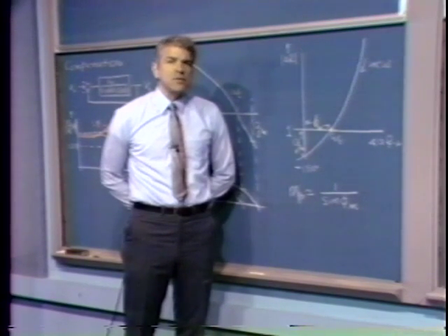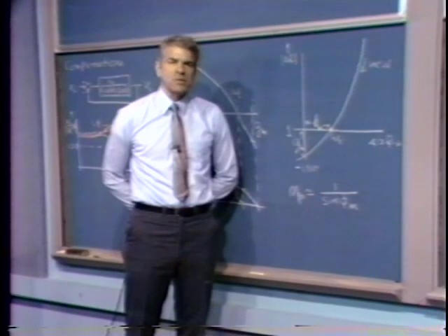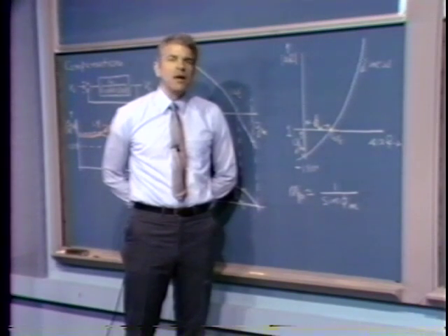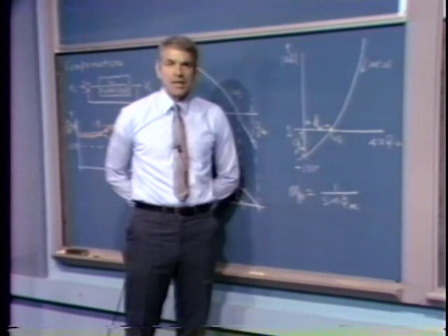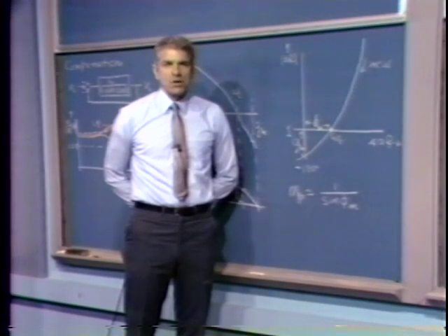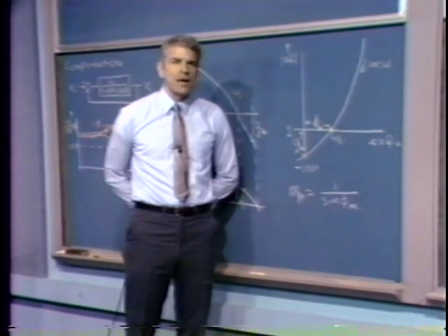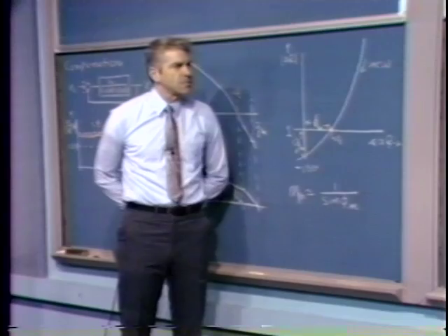Because it's so easy to do, I think almost all of the numerical work that one does with feedback systems really is based on these kinds of frequency domain concepts. We may use root locus as an aid to quickly seeing what's going on in the system and what might happen if we changed a zero location, or what might happen if we change the location of a pole. We can use root locus concepts to explore those issues very quickly. But when we want to get numerical results, when we'd like to determine the correct value for certain system parameters, we almost invariably do that using Bode plot frequency domain techniques.